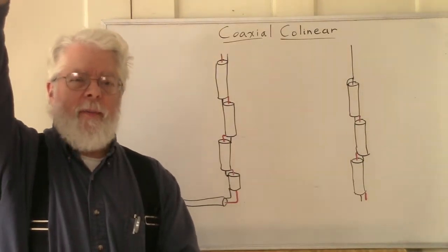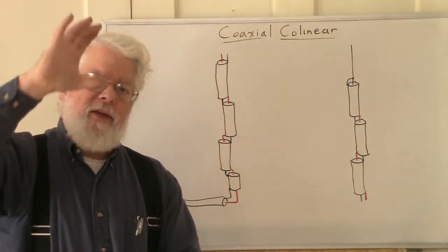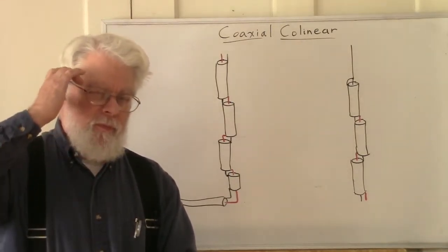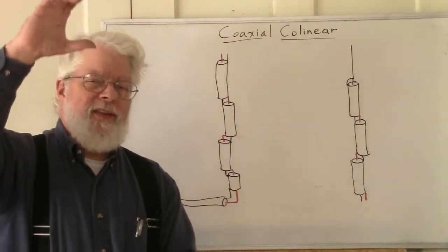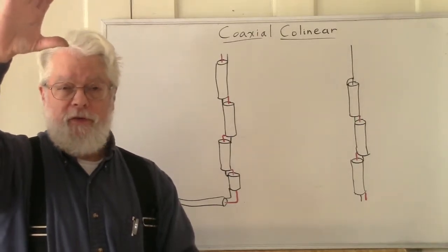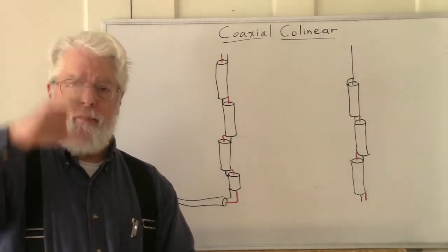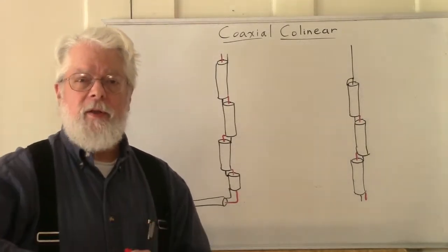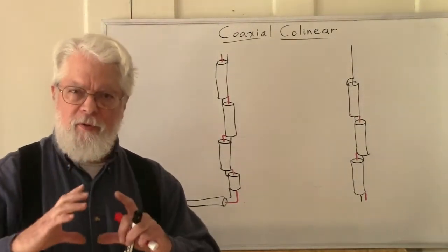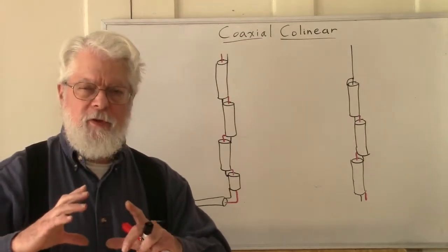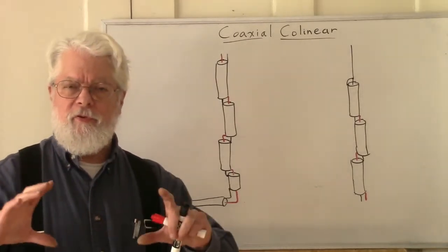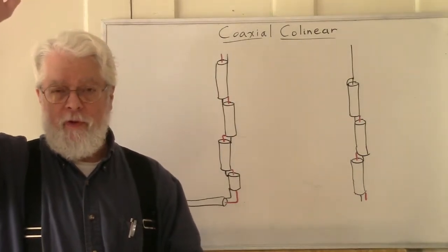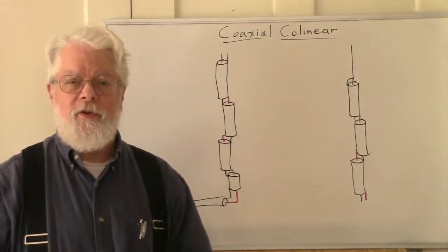Has a very large aperture, and each antenna element has not as much of a decrease in radiating efficiency as you might suspect. Most antennas, as the signal travels along the antenna, the bulk of the signal is radiated from the lower portion where the current is high, and then as you reach the voltage node at the end, it diminishes.